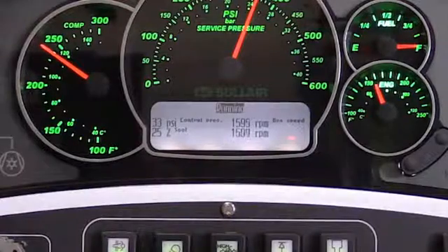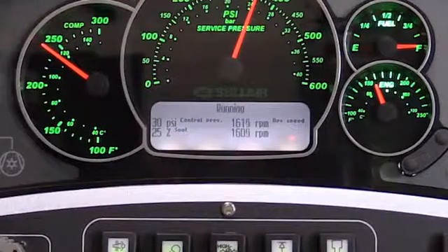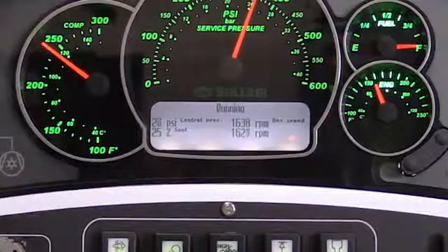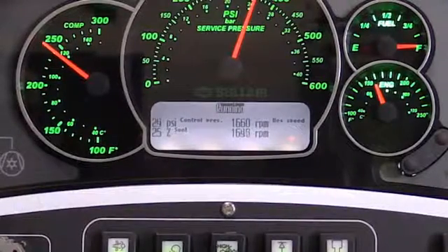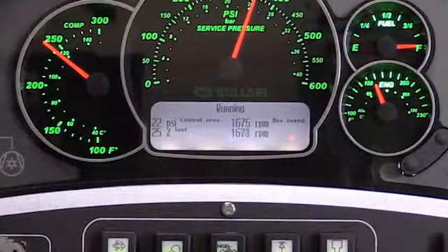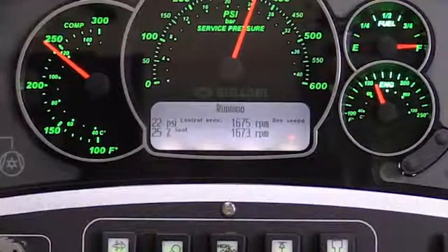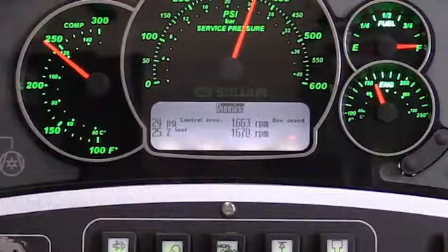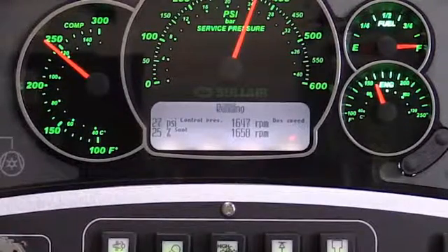The P2 pressure range that C-Pro utilizes to determine desired engine RPM is 0 to 60 psi, 60 psi being minimum idle speed, 0 psi being maximum idle speed. Anything in between would be 1400 and 1800 RPM.